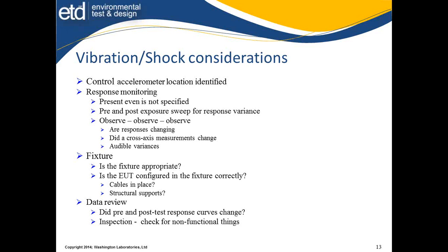Sometimes customers will come in, attach the unit directly, monitor it and say, okay, that didn't work very well. And in reality, they're always going to have shock dampeners. So the harshness of the shock and vibe is not the same as what they tested. So they go back and redesign and get all these things resolved to do something that never would have been a failure had they properly configured it.